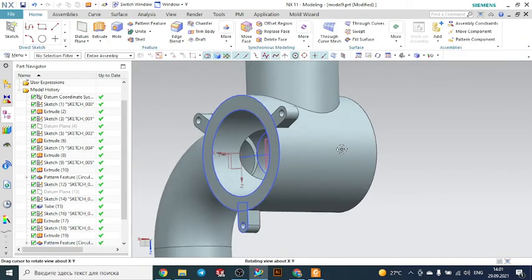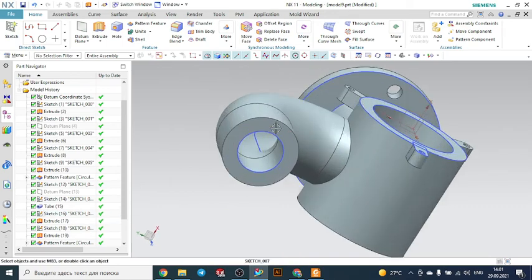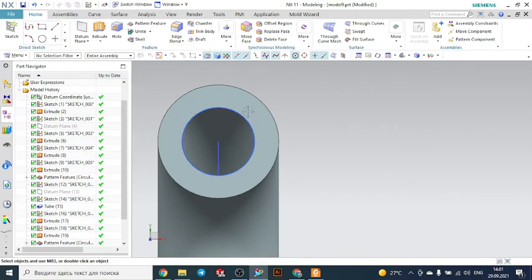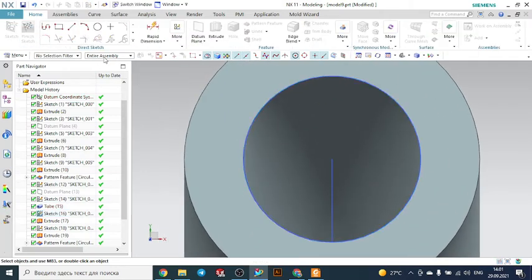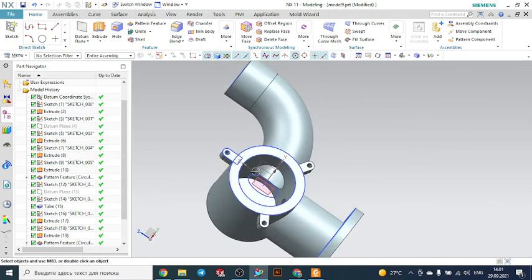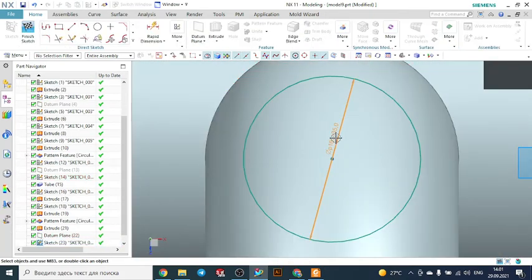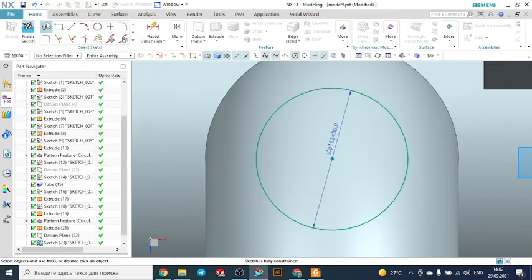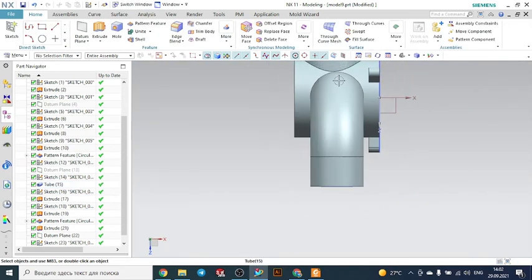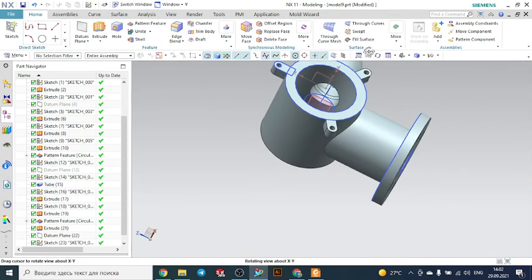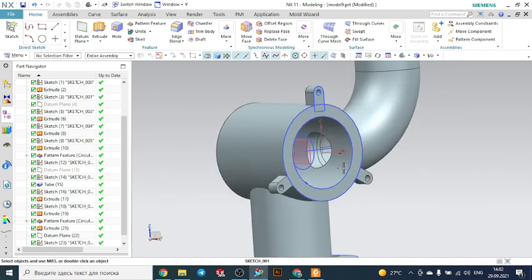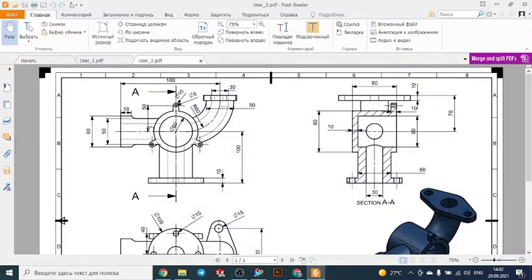Now we will obtain our hole, but the hole diameter is here. Let's check it. It was not 35 but 30. Now we will change this value to 30, so in order to be in the good position, so 30. So finish the sketch. So in this way you see we obtained our hole here. You can obtain it with different methods if one method is not properly defined. So we can go on with this part.